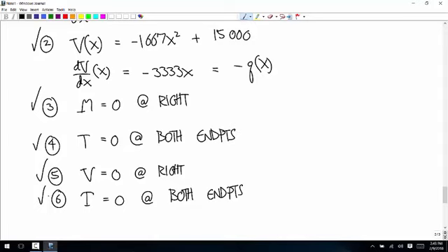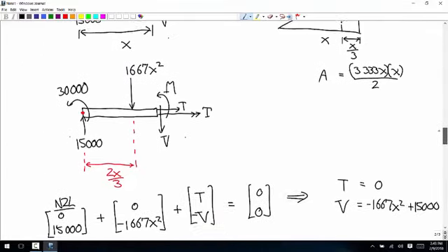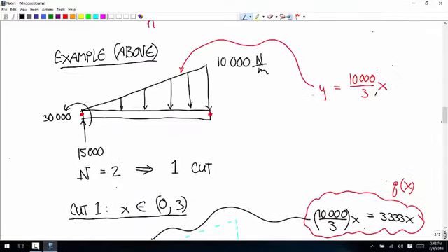But as soon as you put a wall on the right side and didn't change anything about the loads, that doesn't become true. Here's what would happen if this was also a wall. You had this beam in between two walls. First, maybe most importantly, it would be statically indeterminate.